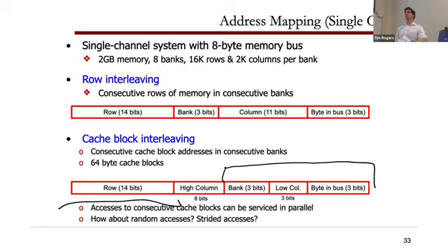Latency wise, what do you mean? So you're saying having those 3 bits at the lower column makes more sense if it's more expensive to stride across banks. Having the second mapping, instead of putting the bank bits in place of lower column, would make more sense if striding across banks is expensive in pure latency. I see what you're saying, for his example of trying to stride the cache line across the bank.